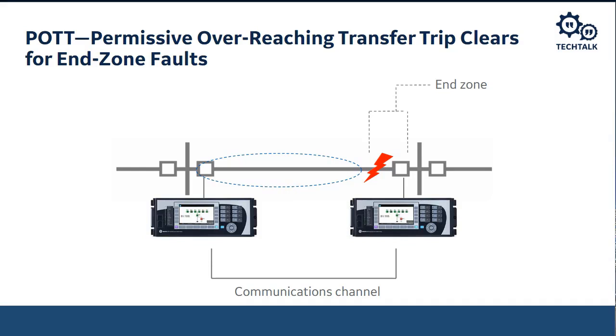And so that dotted line, I can't go all the way to that breaker, because of measurement errors, because of arc impedance, because of a lot of different things like that, I might overreach that breaker and actually trip for a fault on that bus that's at the relay on the right. Now, I won't do that, right? Because then I would lose coordination and I would end up over tripping. I trip equipment that I don't want to trip. So this leaves me a problem.